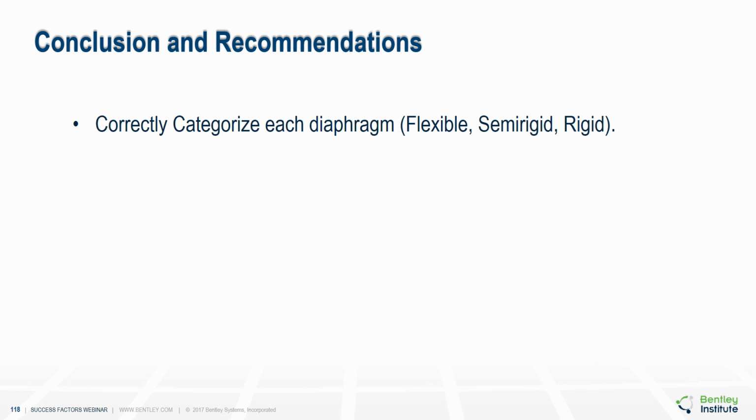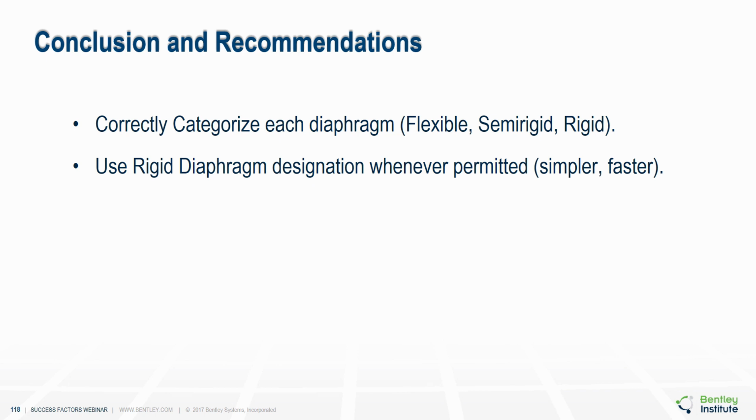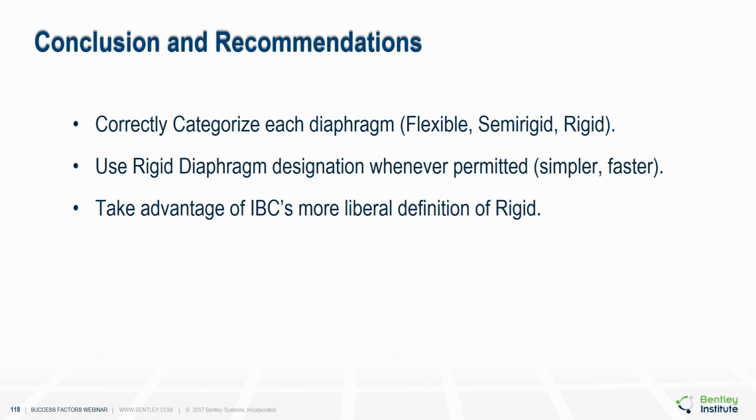Is it semi-rigid or is it rigid? Of course, you need to correctly categorize that. Generally use the rigid diaphragm designation whenever you can because it's simple and it's faster. Take advantage of IBC's more liberal definition of rigid.